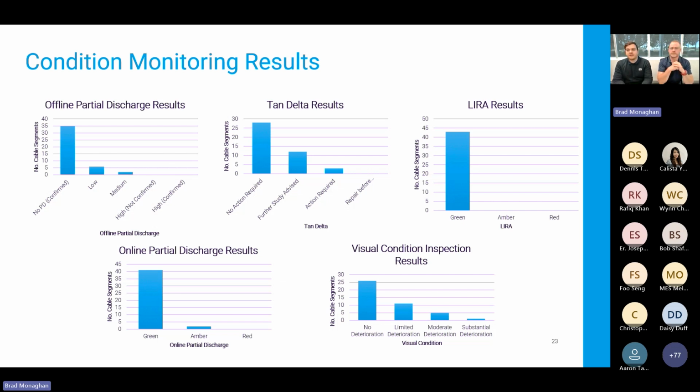And on that, one of the things that's really quite interesting about this particular case study, and the reason we're talking about it, is it has 2 things that are significantly different to most other CBRM models and cable networks. The first is that you could visually inspect the large majority of cables. That is a luxury that most HV networks don't have. Most HV networks don't have the ability to walk the line and to visually see every joint in the condition of the cable. So that was a really good luxury and we could do that.